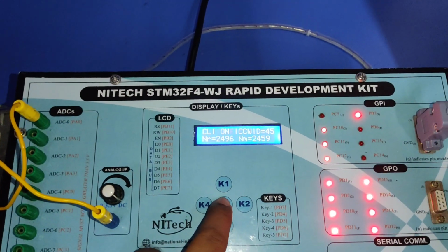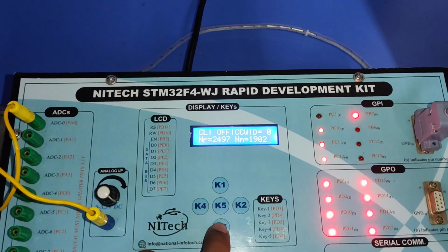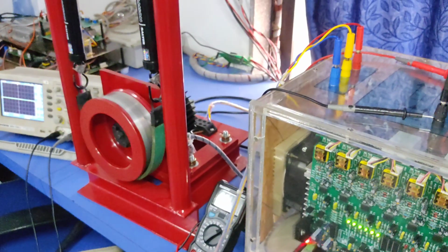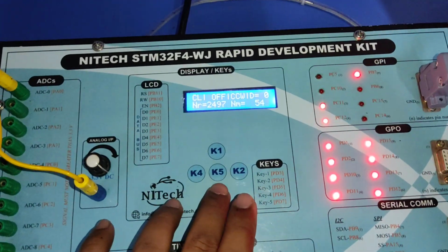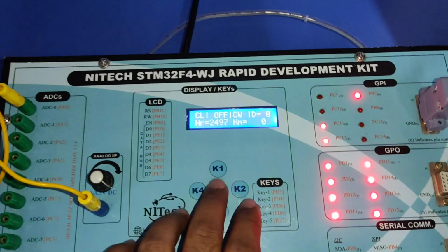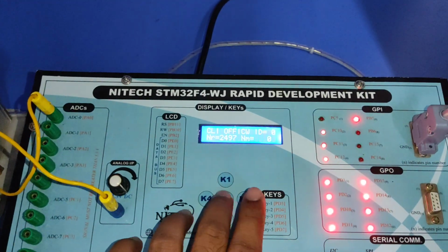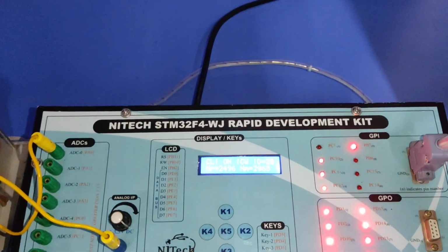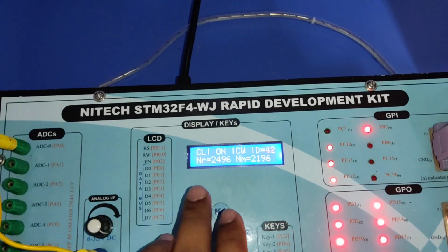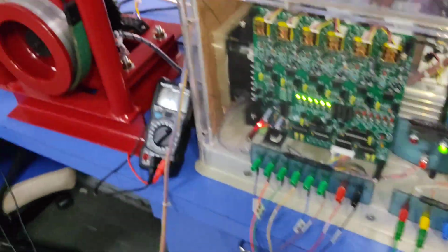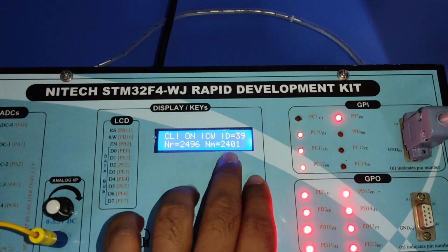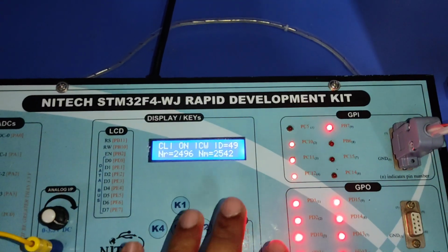Now by pressing this button you can turn off the system and change the direction. Wait for the system to stop. Now you can change the command to the counterclockwise direction, then you can start the motor. At this time whatever last command you have applied will be taken directly. You can see it is started, and duty is around 50.